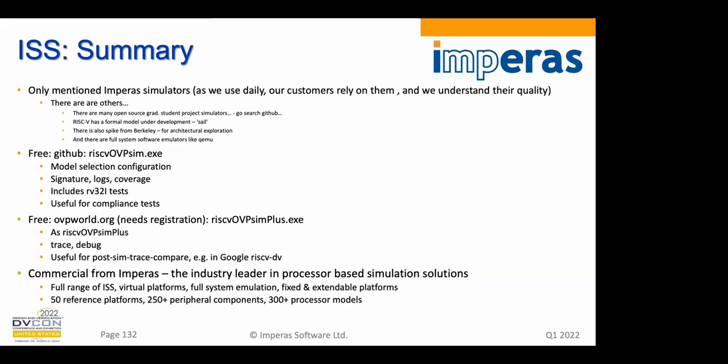And what we showed you here is really a couple of the free simulators from the GitHub, riscvOVPsim, which is really useful for compliance level work. And then the riscvOVPsimPlus, which is really for more detailed simulations because you can get full trace and debug out of it. And that can be used in the Google RISC-V DV instruction stream generator flow as a post-simulation trace compare reference in there. And then we just showed you a couple of things around the Imperas tools where we have a full range of ISSs, virtual platforms, full system emulation, extendable platforms where we have hundreds of models, components and peripherals, and can simulate an awful lot of operating systems running on top of them.